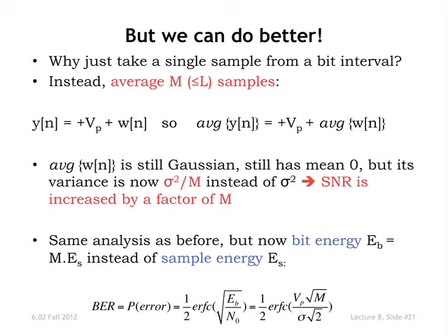So the question is, what does the average do? Why did you want to average them? What was your intuition? Because it would decrease the noise. Okay, so here's the key thing. If you've got independent noise samples and you average them, you're going to decrease the variance. If you've got M independent noise samples from an IID process, you decrease the variance by M. This doesn't hold if the noise samples are not independent. In fact, if one noise sample equals the other, then when you add the two, you get something whose variance is 4 times rather than just twice. So it's critical that these be independent.